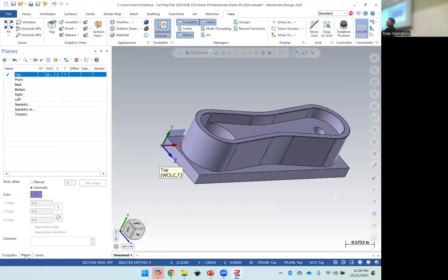So we want it down here, right? Because it's going to sit on the parallels. Also the XY upper left corner of stock. So that's upper when it's sitting in the machine, and left is this side, right? What's the problem with the way it's set right now? Yeah, so right-hand rule, the Z needs to be pointing up where your tools are located, right? So I need the Z pointing up where the Y is.